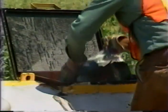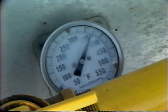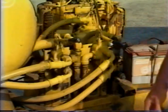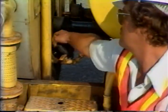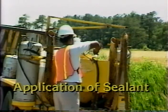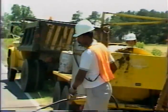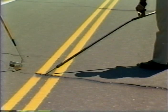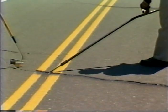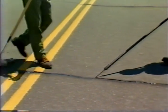Rubberized asphalt sealant requires special equipment for handling and application. Take care to maintain proper temperature of the material. Follow the manufacturer's recommendations for handling and placing sealants for best results. Step 3 is the application of the crack sealant. Place the sealant using an applicator wand attached to a sealant machine. The use of a wand ensures that proper application temperature is maintained and eliminates additional handling of the material.